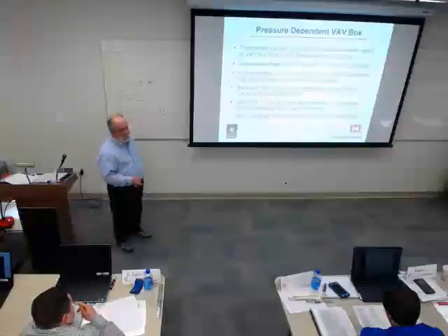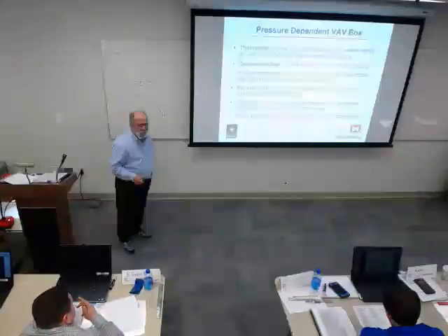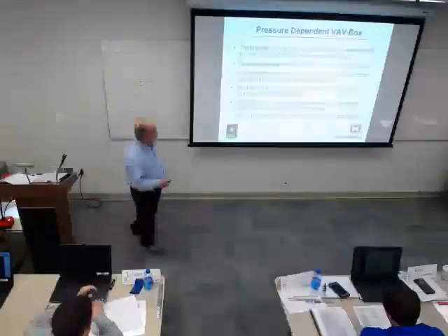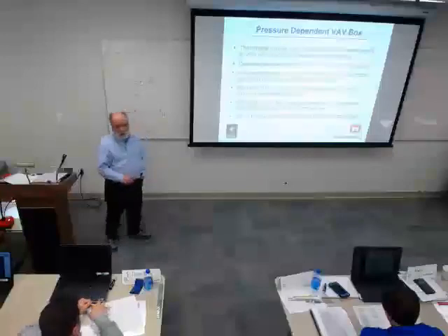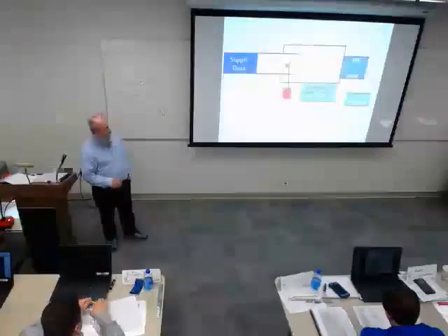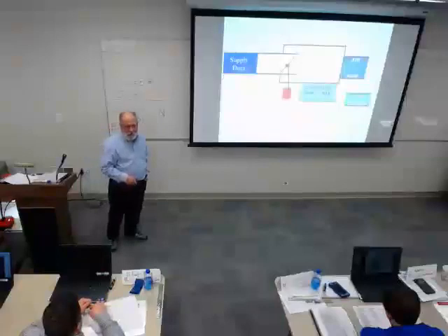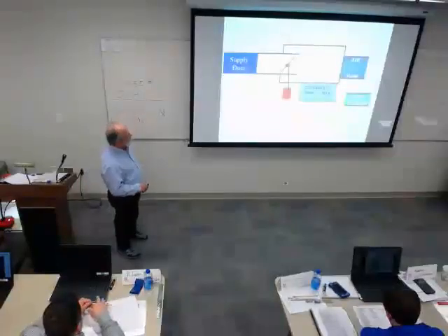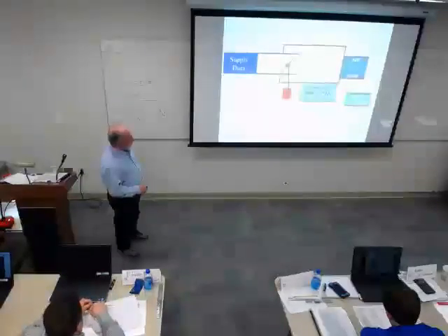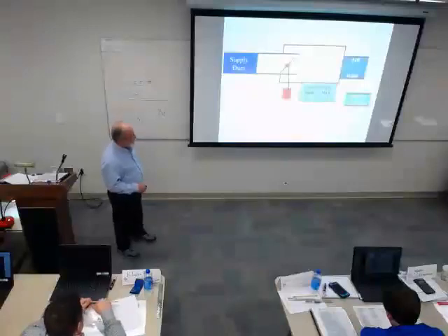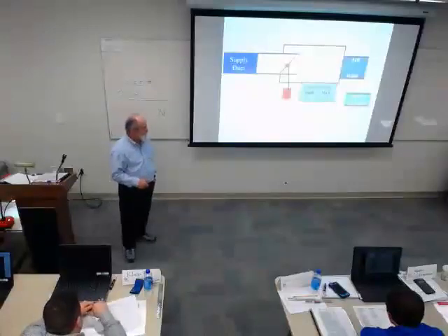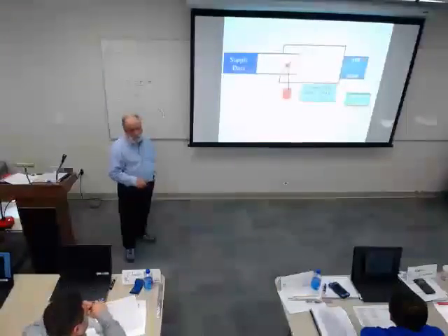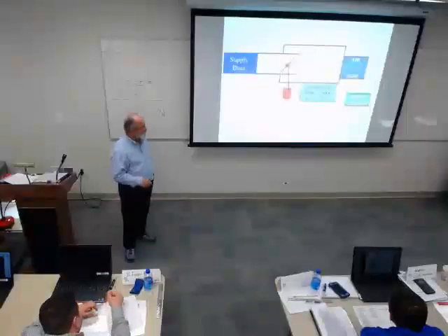And so we strongly recommend against it; I don't know if we even allow the use of pressure dependent terminals anymore. When I started, we did. And yes, they're controllable, but you have to learn to get along with them. So that's what it's like. Air comes in, there's a damper, air goes out, and the space sensor senses temperature and tries to modulate the damper to match what's needed.